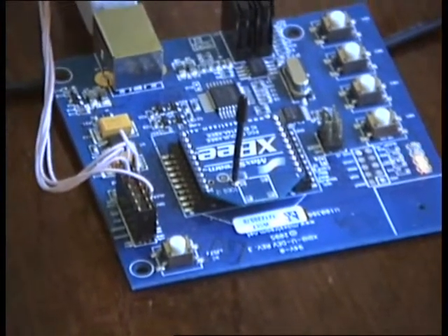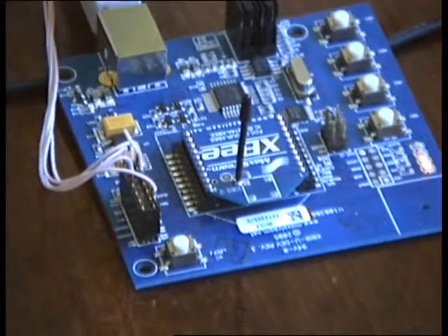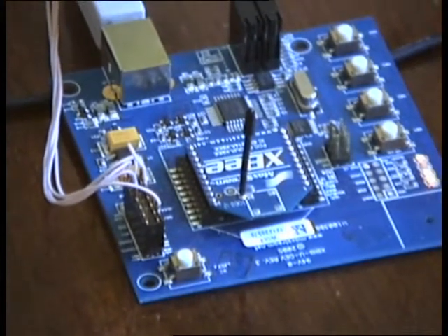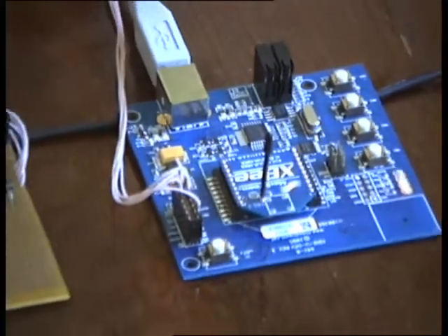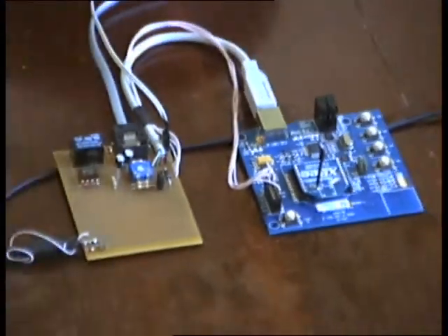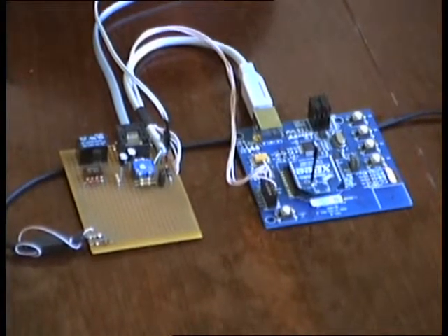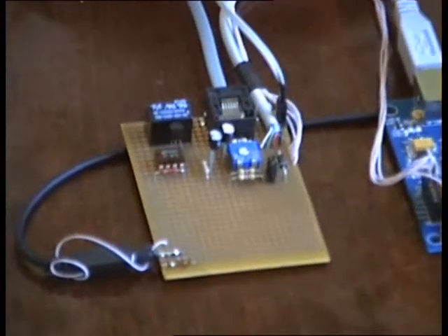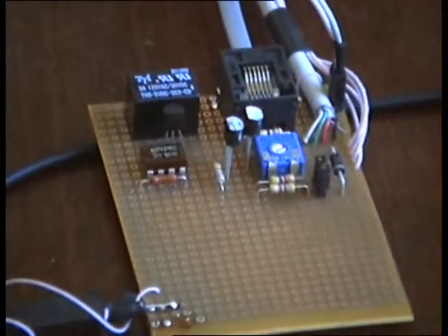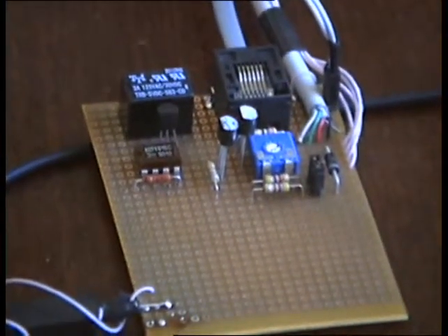The remote XBee module is configured to send the converted value and sensor status to the main controller every second. It also receives commands to switch the water pump on. It works unassisted, without any additional microcontroller. A small peripheral board is used to connect the above mentioned devices to the XBee module.